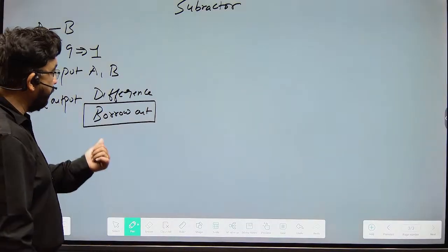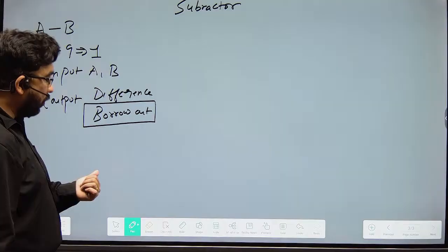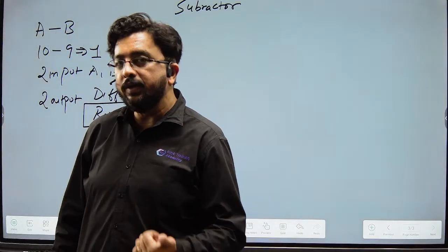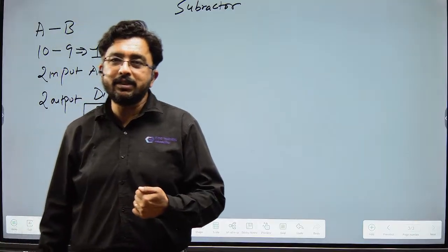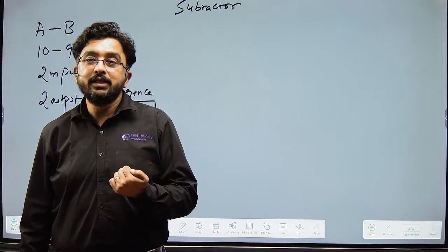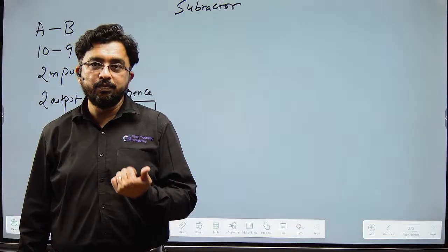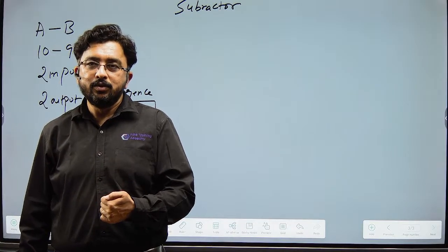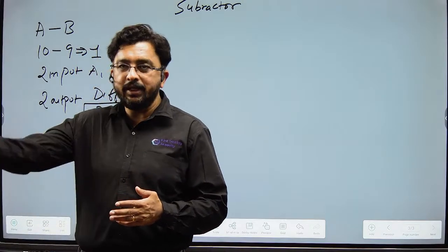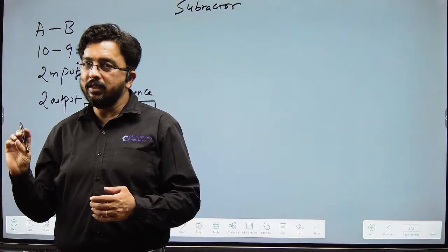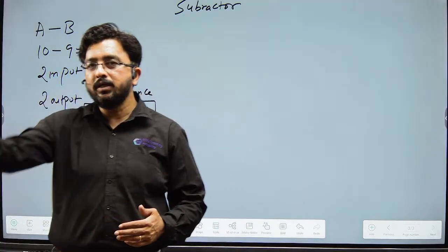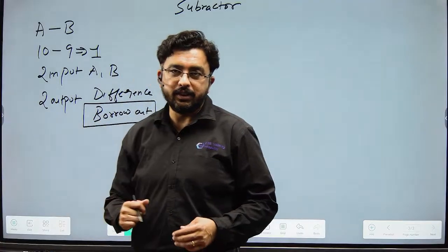If you say borrow, then borrow is used for borrow in also and borrow out also. Similarly, just like carry, there is carry out and carry in. Both have different purposes. Carry out becomes the carry in, and carry in is then calculated with A and B, giving you the output and again the carry out signal.